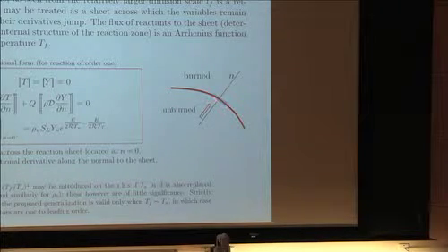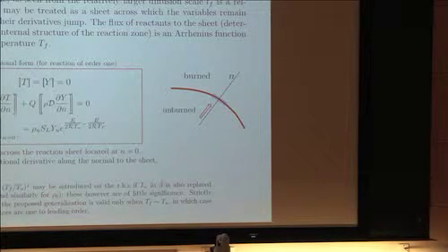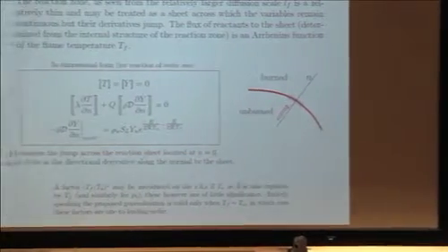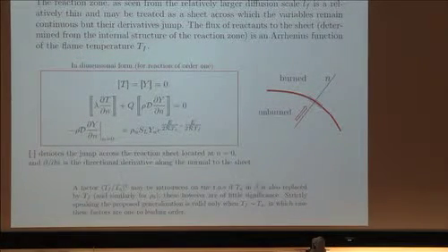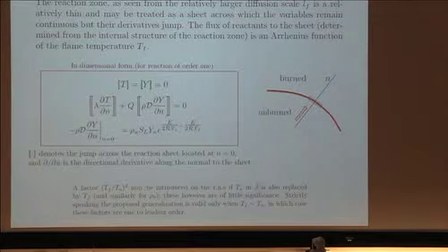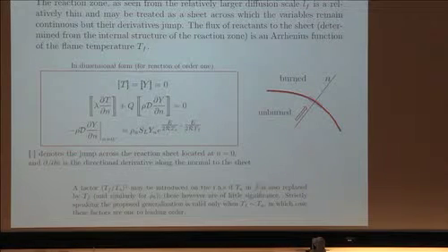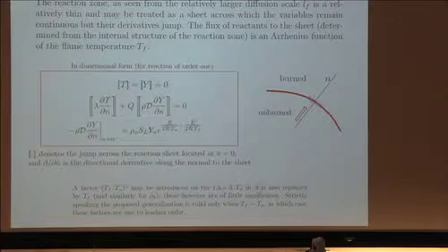One is that the coordinate needs to be normal to the flame sheet, or I should be more accurate by saying the reaction sheet. And the second thing is that I should allow for the temperature not to be exactly adiabatic, but a little bit different, and therefore I will call it TF, because once the flame is curved, there may be a gradient of temperature in the transverse direction or other effects that will lower or increase the temperature.